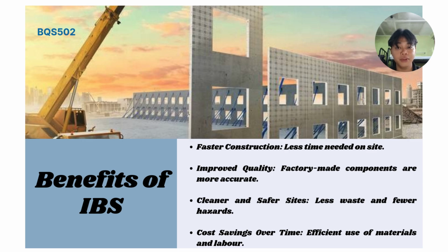Let's continue with the benefits of IBS. IBS brings many advantages to the construction process. Firstly, it reduces construction time because most of the work happens in the factory. Secondly, it improves quality since components are produced using precise molds and machinery. Another benefit is a cleaner and safer site as there is less material waste and fewer workers needed. In the long run, IBS can also save costs through better productivity and reduced rework.